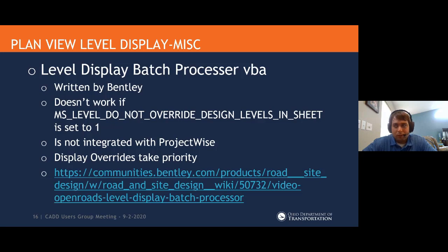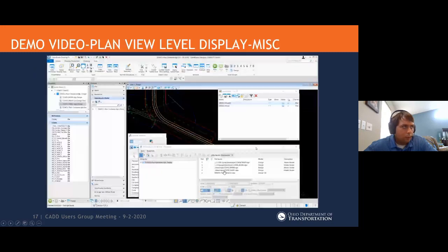But as you see, we can easily set those differently per individual reference. So it doesn't check that per reference, so it'll act like it's working. But if your display override is never, then it's not really going to work, because the display override is going to take priority over it. So I think we're going to add this into our standards, but I wanted to make sure I outline those kind of caveats if you go to use this. I think I have a video that briefly shows that.